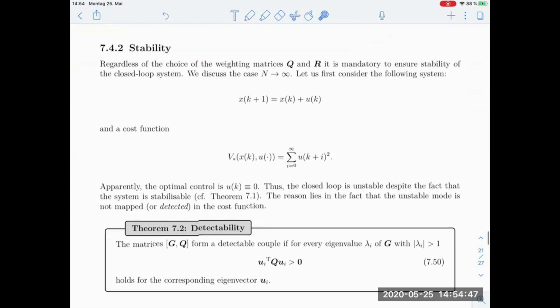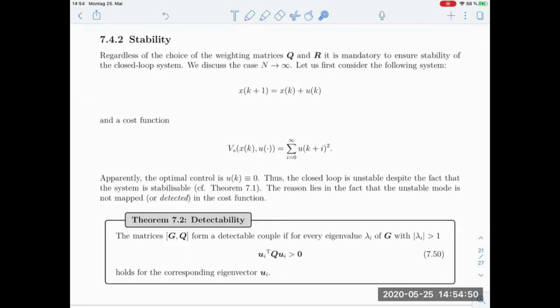All right, finally, to sum up the necessities for an LQR controller to stabilize the system, we've seen now that we have several ingredients that we need. Let's look at one more pathological case. When we have a very simple system, which is perfectly controllable and it's marginally stable, so we have an eigenvalue of 1 here, and we can control it. That's a system which is nice to formulate a controller for. We can just stabilize the system and work with it very nicely.